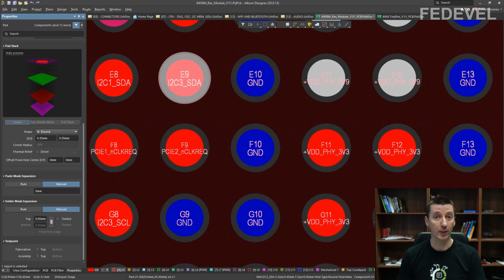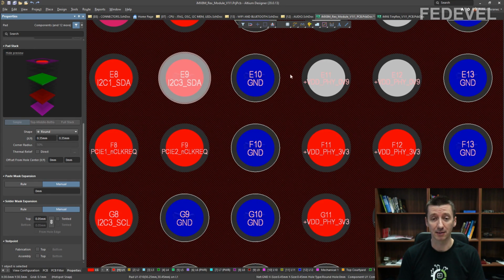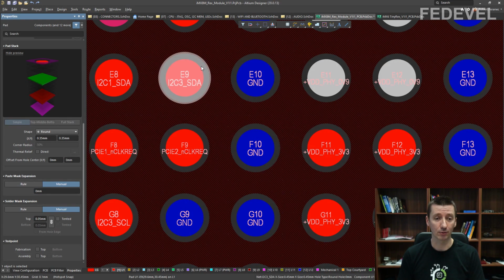Okay, we learned almost everything about these vias in pad. I was still curious to know, because we were speaking about the pads under BGA, I still wanted to ask a question about mask opening. How small a mask opening is recommended to use around the pad, because usually there is not really much space under BGA, so the mask opening you would like to use maybe as small as possible, and I wanted to know what the limits are. So here is the clip where Mike was speaking about this mask opening around the pads.